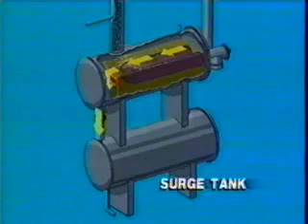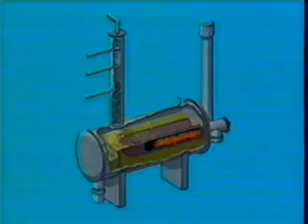If all natural gas came out of the ground in pure form, we wouldn't need this glycol dehydration unit. But almost all natural gas streams leaving the reservoir contain water vapor, and some even contain free water. As natural gas travels up the wellbore to the surface, it cools due to pressure reduction and conduction of heat to formation walls. When it reaches the surface, the natural gas is usually saturated with water vapor, and additional cooling causes free water to form.